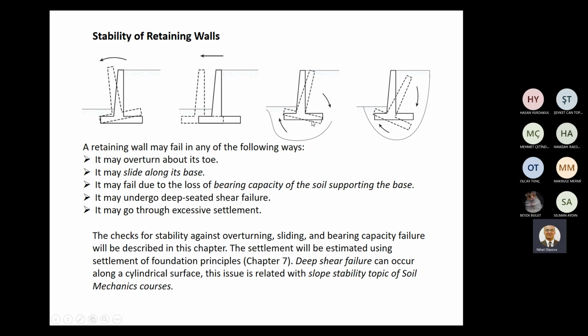The wall may fail due to loss of bearing capacity, it may undergo deep-seated shear failure, and also excessive settlement may be a problem for retaining walls.